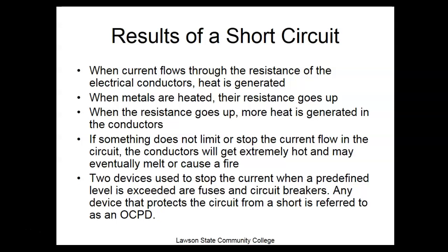Short circuits: when current flows through resistance in electrical conductors, heat is generated. When metals are heated, the resistance goes up. Resistance goes up, more heat is generated. If something does not stop the current flow, these conductors are going to melt and cause fires. A lot of times you'll see on the news where they say this house caught on fire and it was an electrical fire. Well, the problem was a short circuit.